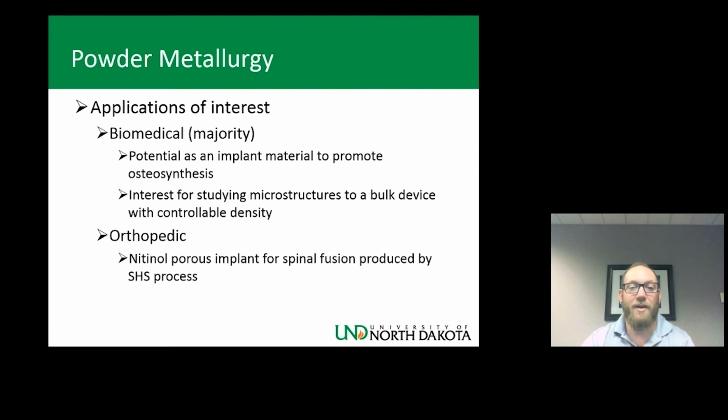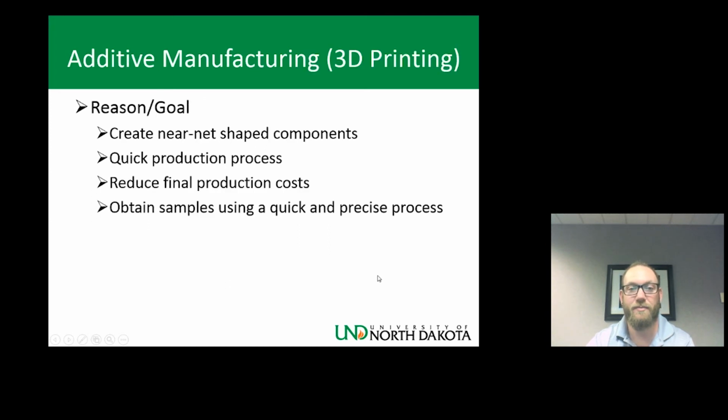The main application of interest has been in biomedical, and they have the potential to use these as implanted material to promote osteosynthesis. And the orthopedic industry has implemented powder metallurgy for creating a nitinol porous implant for spinal fusion, which is done by the SHS process.